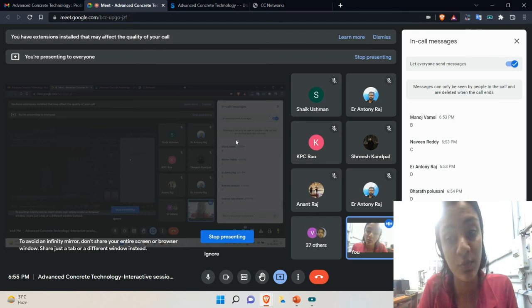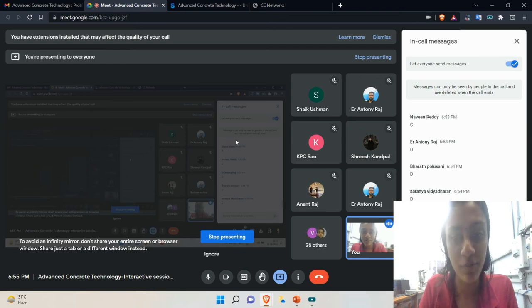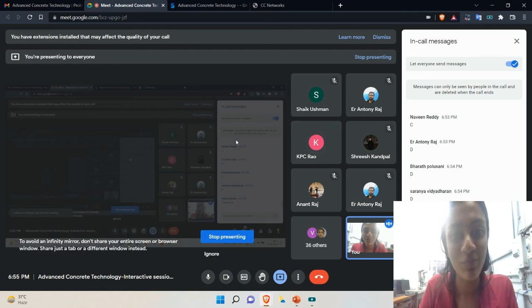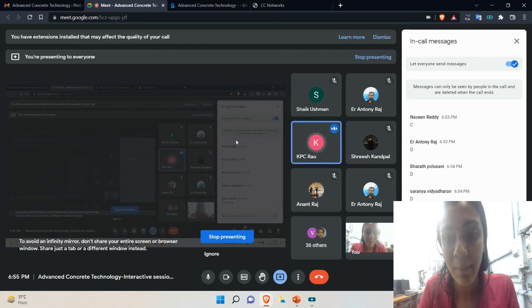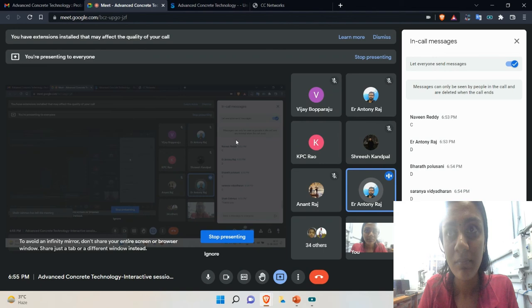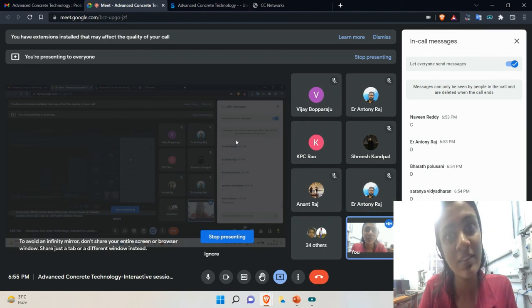So what you are asking is from the live session with the professor, right? Yes, ma'am. Whenever we have done it in our colleges, we have done it on concrete cubes. Nowadays we do it on mortar also. Are the specimens created of the same size, or can we use different sizes? It will be 70.6 mm for mortar cubes. If it is a lime cube, we can go for 50 by 50 as well. We just need to give a proper loading rate.